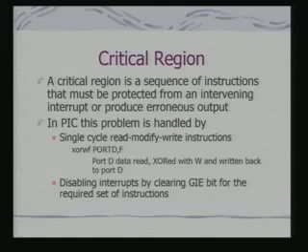So read, modify, write instructions help you to implement critical regions, particularly with reference to your external world and external inputs. The other thing is obvious: if I disable my GIE bit over a range of code, I shall ensure a critical region. But at the same time, in this case, I am increasing the interrupt delay. So that constraint I have to keep in mind. Also, I have told you that we can also use a swap instruction to implement this kind of synchronizing primitive to ensure correctness of critical regions.